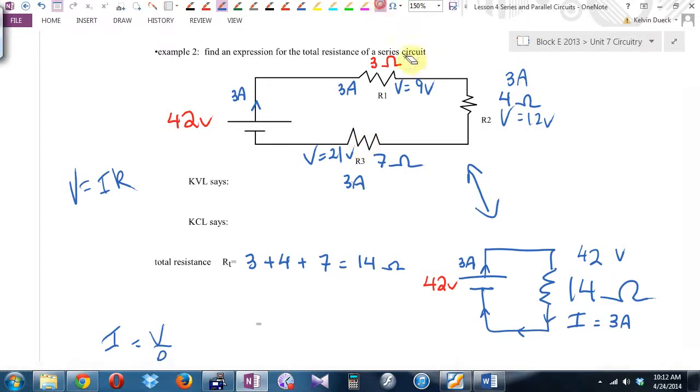So are you okay with my mathematical equivalent down here? Because it's 42 volts high and mathematically I only have one hill, I must lose 42 volts, right? And so then I went V divided by R. Total current is 3. How many amps in this resistor? 3. How many ohms? I times R. Got to be 9 volts, right?